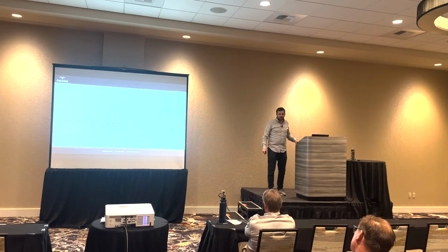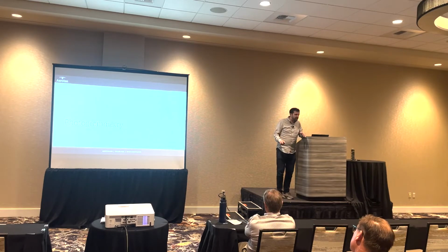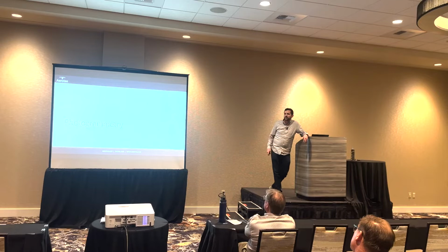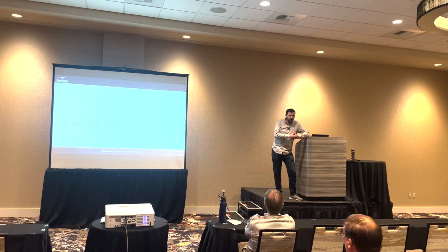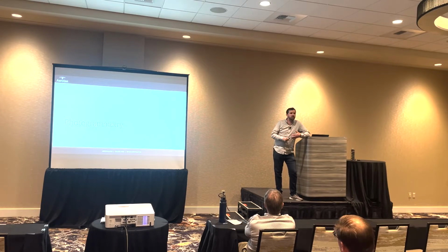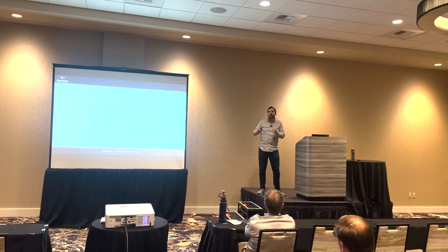So let's start with photogrammetry. I know you probably weren't coming here to get a talk on photogrammetry at least, but as I've said a dozen times before at this point, photogrammetry is really important because all of our research has shown that right now, with the current state of technology, photogrammetry, drone photogrammetry can still provide higher quality deliverables than drone-based LiDAR on hardscape.